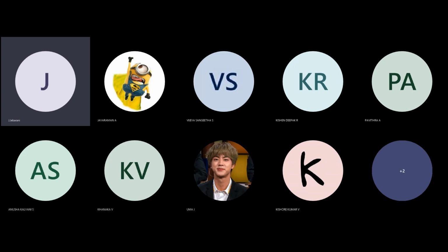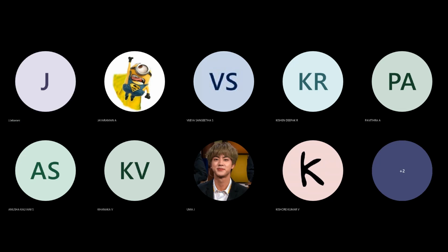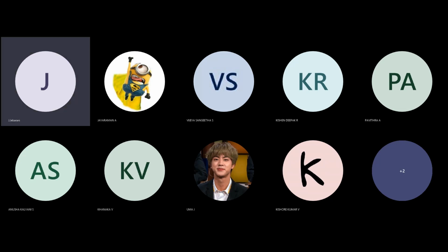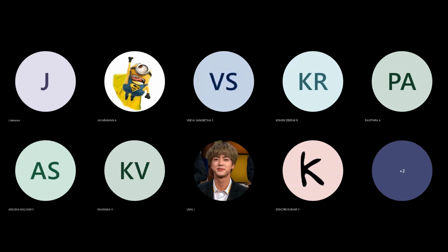But in the water assisted injection molding technique, they are using 4350 psi. Because of the high pressure, the orientation of the molecules is also very high. So due to this, the products produced from the water assisted injection molding technique have somewhat higher mechanical properties when compared with products produced from the gas assisted injection molding technique.